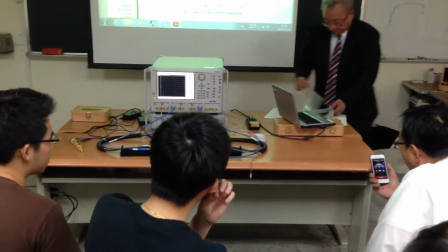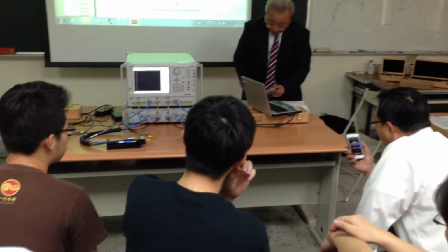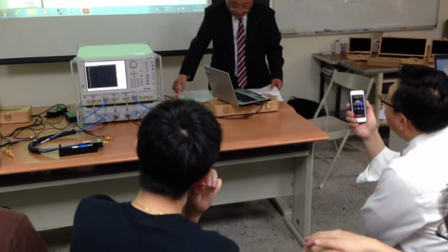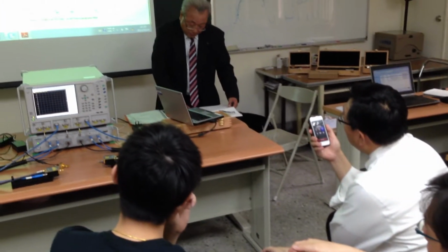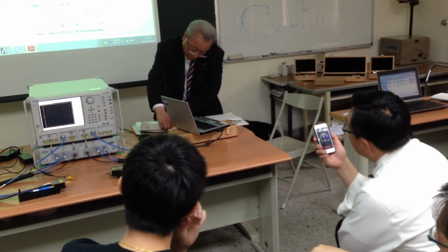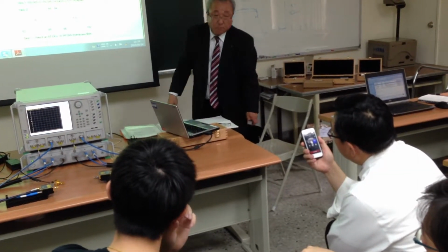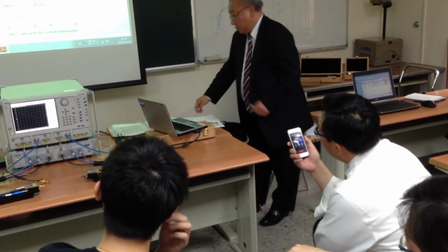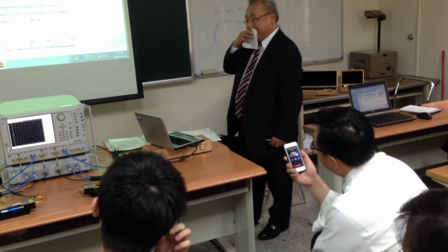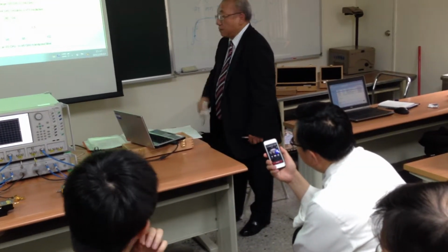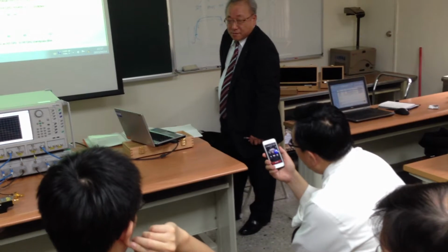They use a broadband filter, for example 80 to 110. Based on our filter selection guide, the multiplier factor is 11. So their question mainly is, can they save cost by selecting a filter to cover the whole 80 to 110 gigahertz to construct their composite receiver?